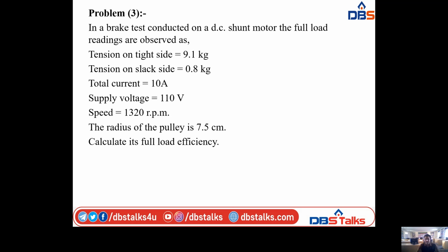So that is equal to RA value, they already gave 0.4, plus RSC value, it is given, 2 into 0.375, into current is 40 whole square, plus 32 whole square into 0.4. Finally, we have the total copper loss, that is 1840 plus 409.6, that is equal to total copper loss 2249.6 watts.